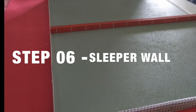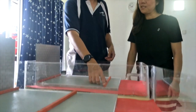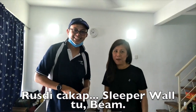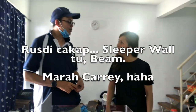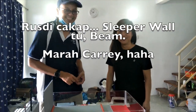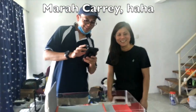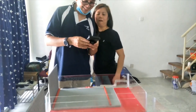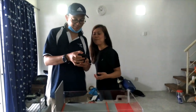Slipper wall. The main purpose of slipper wall is to create ventilation and avoid condensation. For suspended timber ground floor, slipper wall in honeycomb design is necessary. The other function of slipper wall is to support the joist in such a way as in turn allows the joist to support the weight of the floor itself and any live loads such as people and furniture.